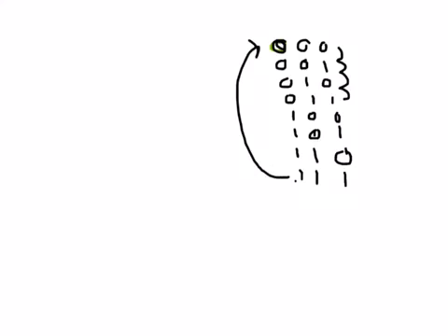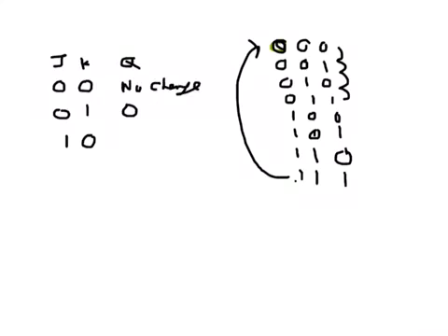Now, remembering the flip-flops, if I remember the JK flip-flop truth table, this is Q. So 0, 0 gives a 0, 0, 1 gives 0, 1, 0 is actually no change, sorry, 1, 0 gives 1, and then 1, 1 is toggle. That's how it was, the JK flip-flop.